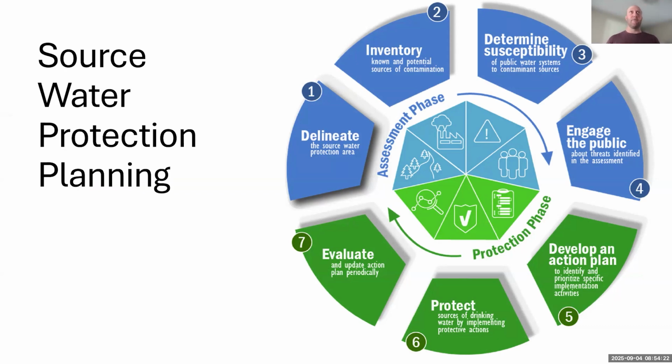So the first phase is to delineate the source water protection area. What is the area that our water is coming from that we need to protect? Figure out what that is. And then inventory the known potential sources of contamination.